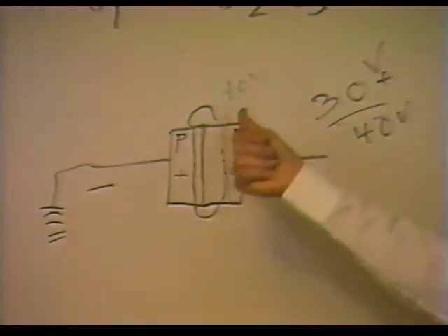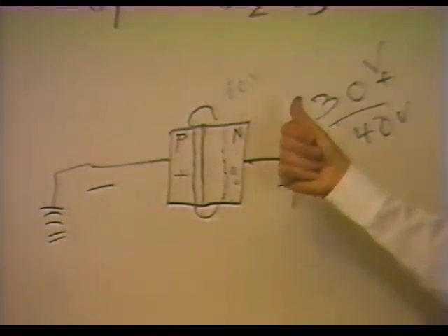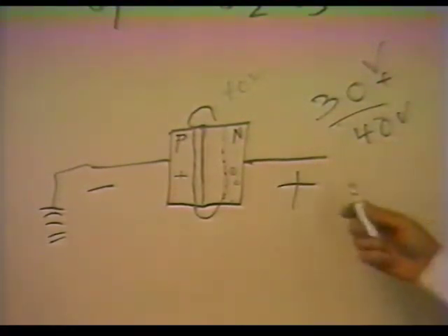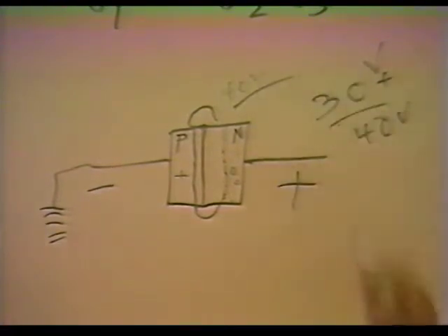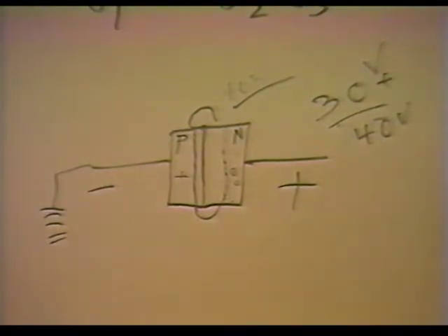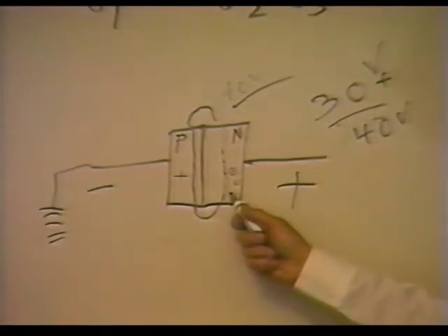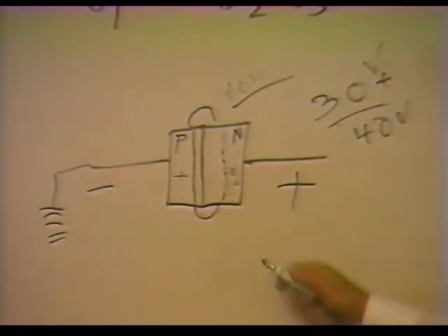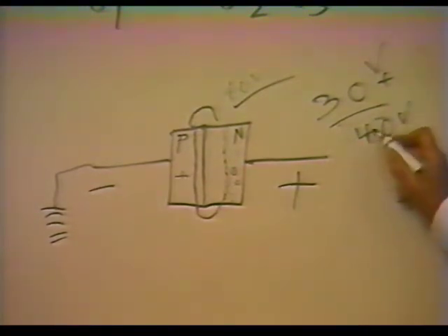And now we're creating electron-hole pairs, or we are creating more carriers. So the reverse voltage now has given enough velocity to the carriers and has started to pull off and move the carriers very rapidly toward the junctions. And the current now will start to increase. So the current goes up.